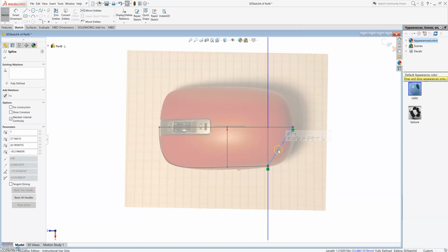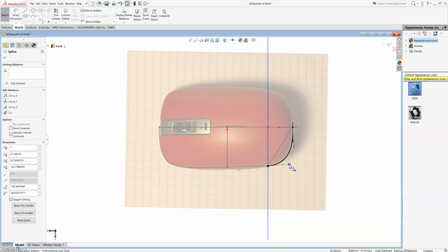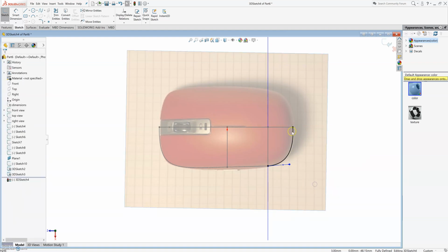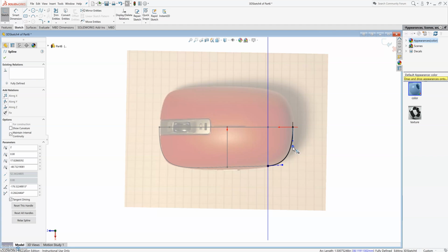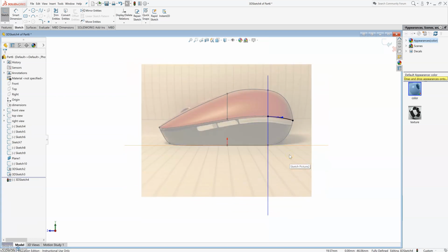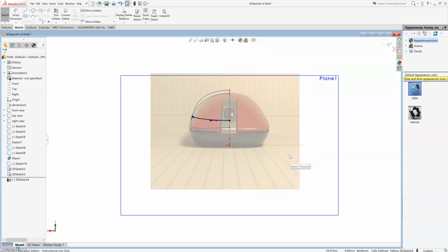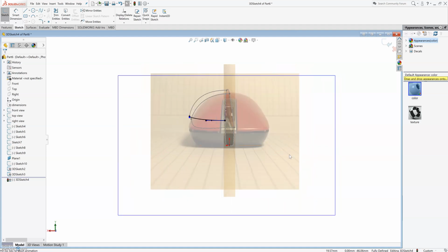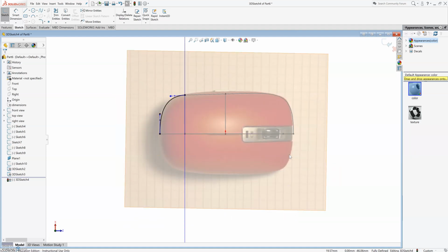Let's go to my top plane, top view. Okay, and then this one, I'm going to make it, again, you have some other relations here you can add for 3D sketches. So I want this line to be coming straight out in this direction, which is the x-axis if you look at this bottom left-hand coordinate system. So I want this to be along the x. So that's a constraint I can add. And that looks pretty good to me. That's a tough view to see, again, because this is the front, so that's not going to really give us any information. But I like that.